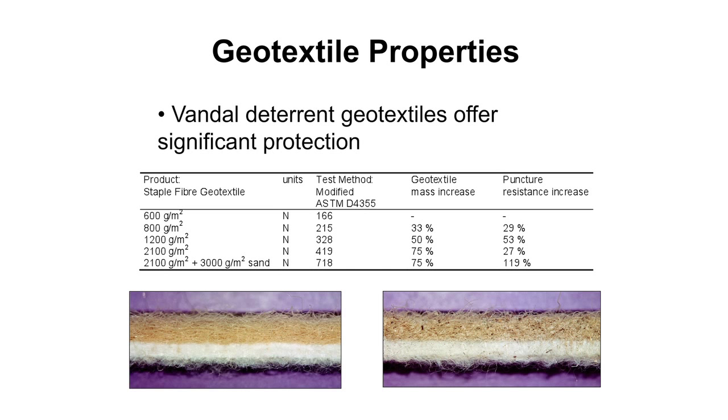Now, while that geotextile does provide some strength, the main strength is held in that main area. What that does is just protect this geotextile. It protects it from knife cuts. And what we found was that once you get a knife and you try and slit it, because it's trapped so much sand in that, your knife blunts off very quickly.